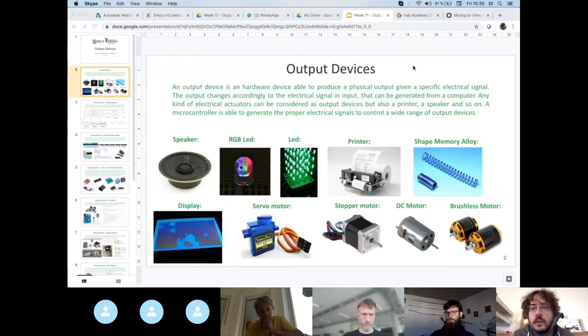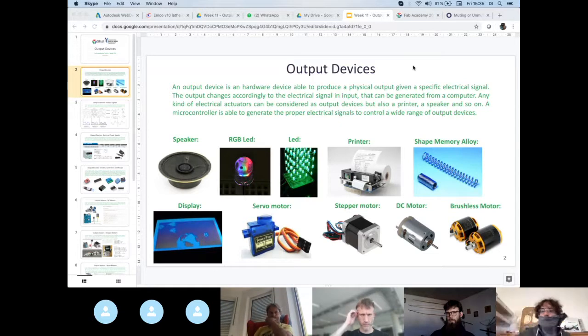We didn't need full rotation. We needed something that was going up and down, something that doesn't require a really long motion, or that requires a very simple motion. It can be like a vending machine that opens and closes the bottom so a product passes. Something that needs to be actuated in a precise way, but maybe doesn't have a lot of motion. They usually use this in walking robots, for example, these spider walking robots, where the leg has to do a limited movement. But if you go with the bigger servo motors, of course, they can do 360 degrees. Okay, thank you.